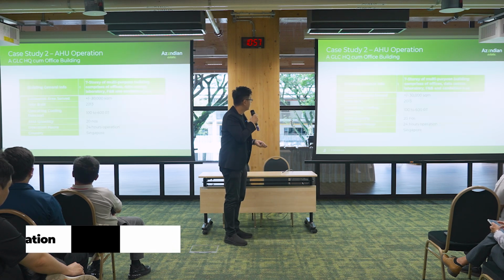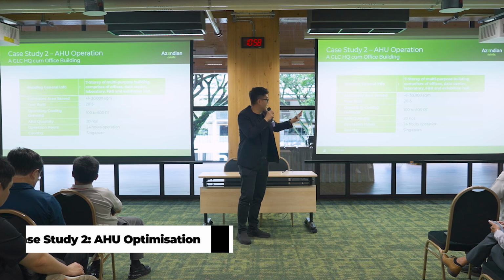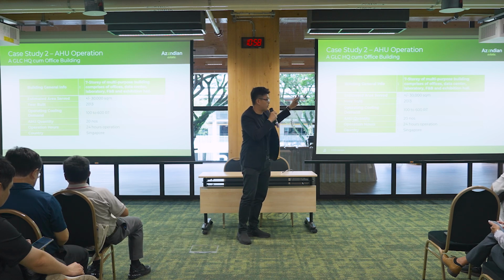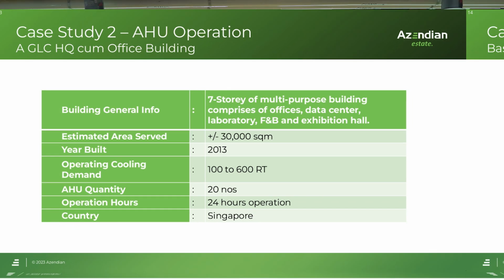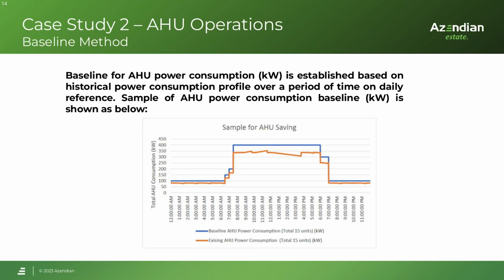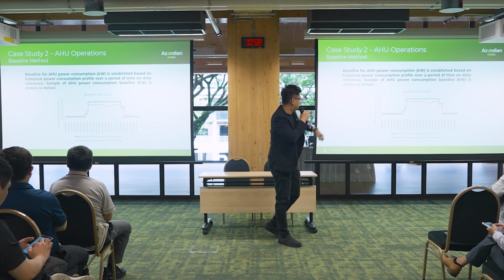Okay, second case study. I'll quickly touch on this. So this is on AHU operation. We optimize how the AHU is being operated. Because of the limited sensors available on site in this specific case, we use a simple kilowatt method in time series to construct the baseline.